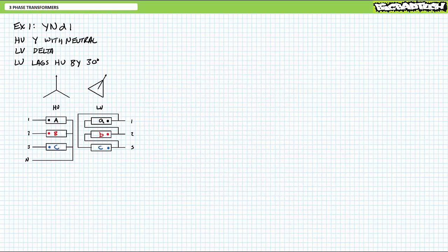Anyways, don't stress out too much about drawing a simplified connection diagram from scratch, because again, only the most sadistic of instructors would make you do that. But do stress out about the proper interpretation of an already constructed simplified connection diagram. Most of the time, you'll have a simplified connection diagram on the transformer nameplate available, and it's up to you to hook it up exactly as illustrated with 0 points being awarded for creativity.